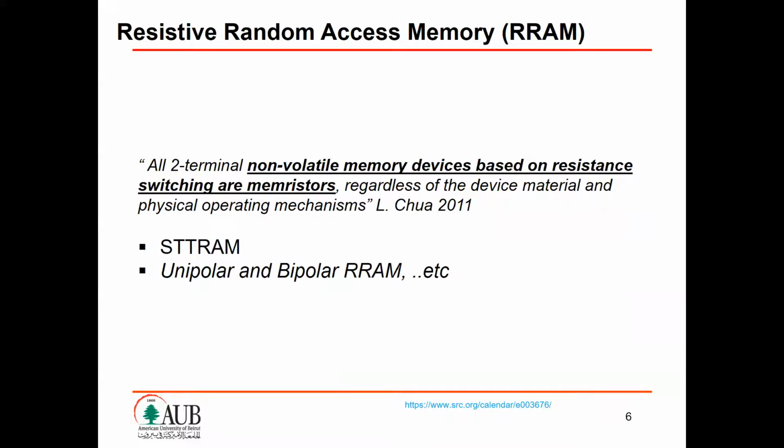They said, well, anything that is a two-terminal non-volatile memory device is a memristor. Okay. There are different types of memristor. Some of them rely on magnetic properties, and some of them rely on the dielectric or the oxide properties. Meaning the physical structure is made differently. With the difference in physical structure, the range between R low and R high differs. For example, this one say from 1K to 10K, whereas the range for this one could be, say, from 50K to 1 meg.